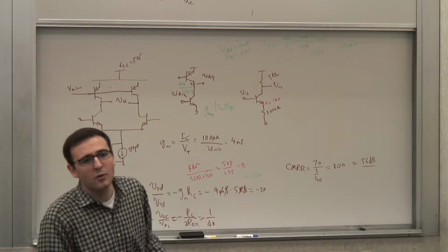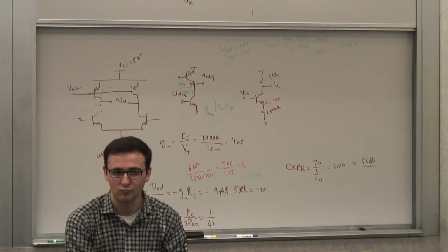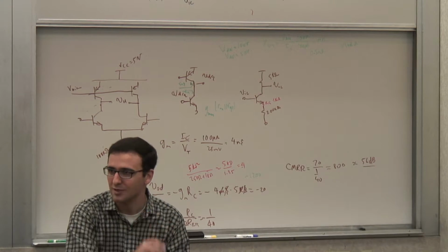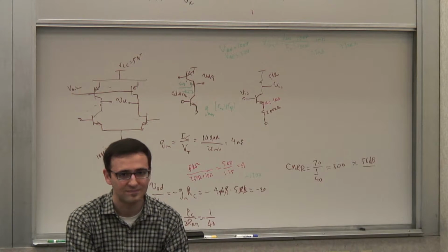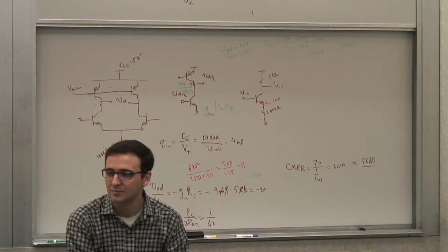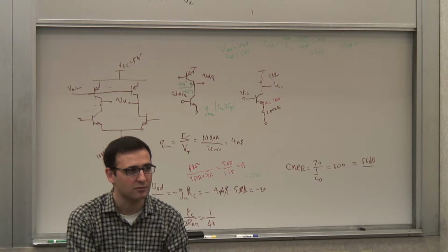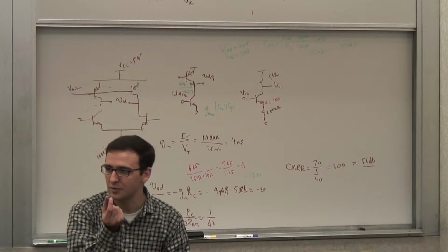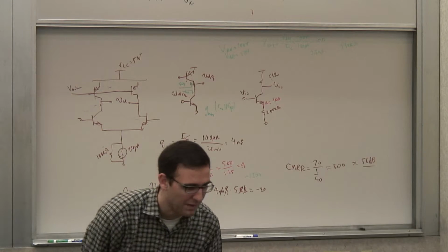Okay. Now you want to have an output voltage range of 5 volts. Right? Your supply is maximum 5 volts. So what does that mean in terms of the input voltage range? 5 millivolts, right? So you see, it's very fundamental to the fact that you have higher gain that your input voltage range will become smaller and smaller. Nothing magical there.